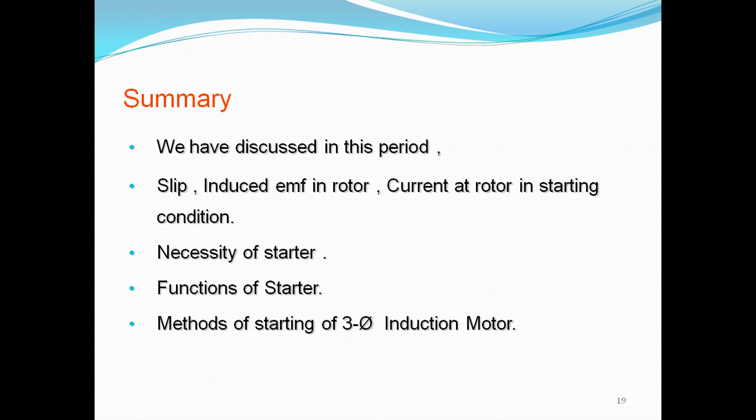When the motor reaches 70 to 80% of the rated speed, we gradually reduce the resistance.